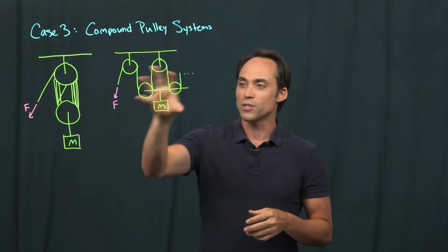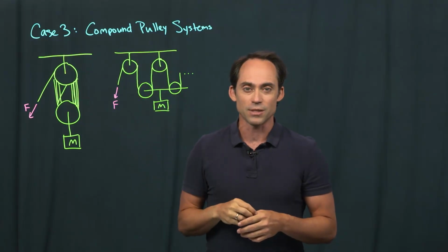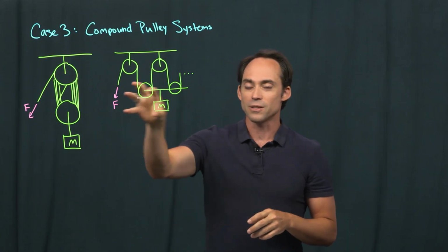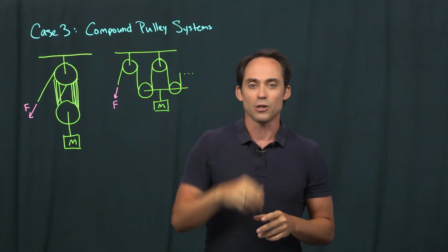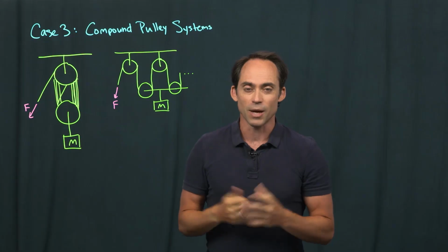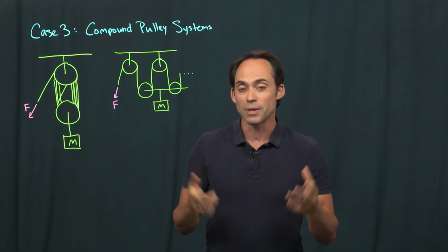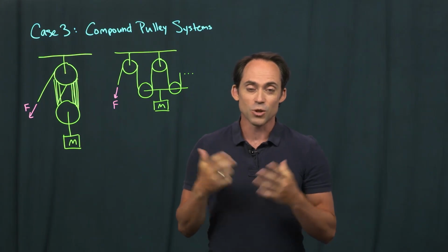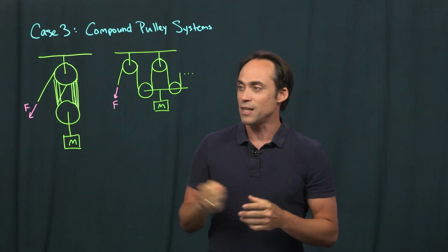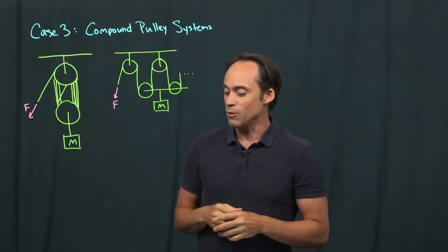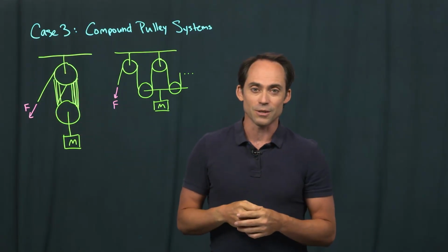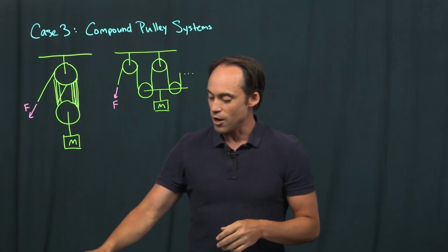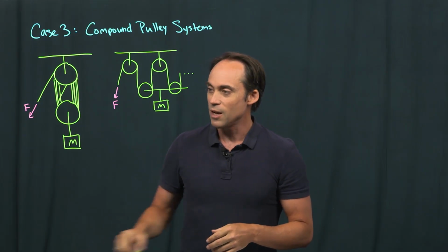This is more schematic, showing how you could break up this system into individual pulley wheels, some of which are fixed, some of which are movable, and this can continue on as many as we want, depending on what mechanical advantage and what limitations we actually have on the support structure for the system. So to see how we can break this down, let's just take the case of what I've drawn here, which is a 4-cable system. We'll call this a 4-fold purchase, and we can draw similar kind of force diagrams for